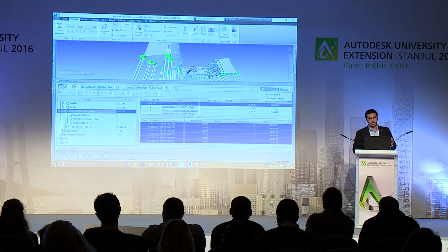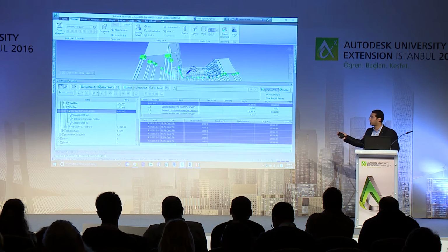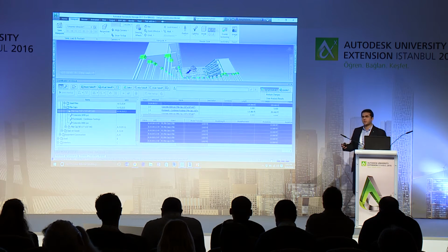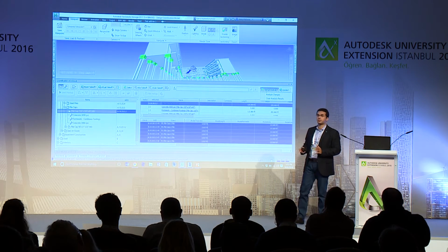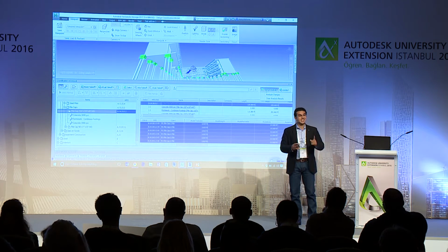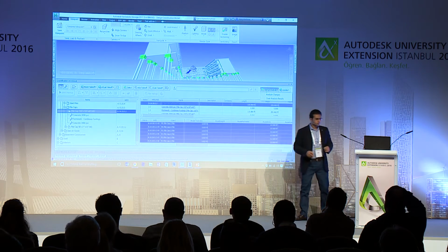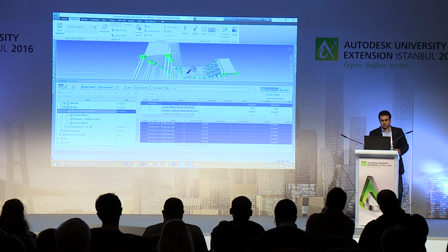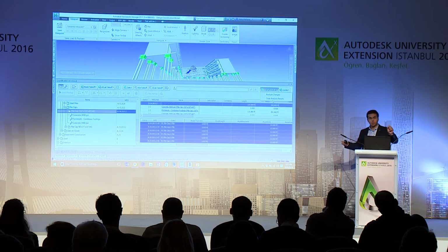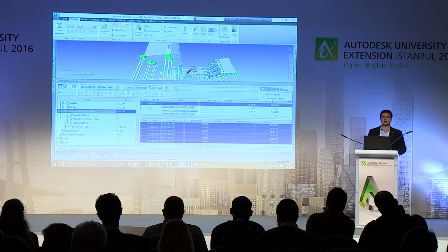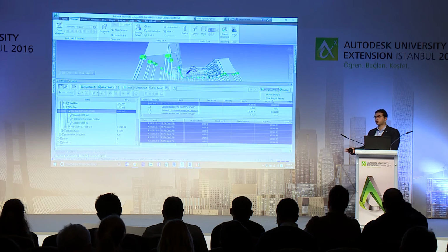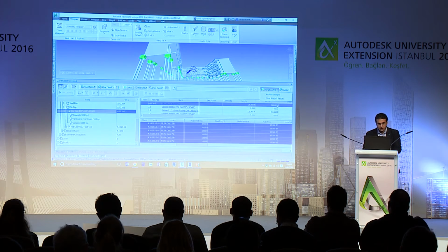One of the things that is available in Navisworks quantification takeoff is that it supports the BIM workflow as well as the 2D workflow, which means if you still have part of your project available in 2D CAD only, you can take off the quantities in a single quantification workbook here. We don't have time, unfortunately, to view it, but if you have a 2D drawing, you have different tools to measure lines, to measure areas, fills, etc., as you will have in any different QTO application that is designed for 2D workflows. Last but not least,